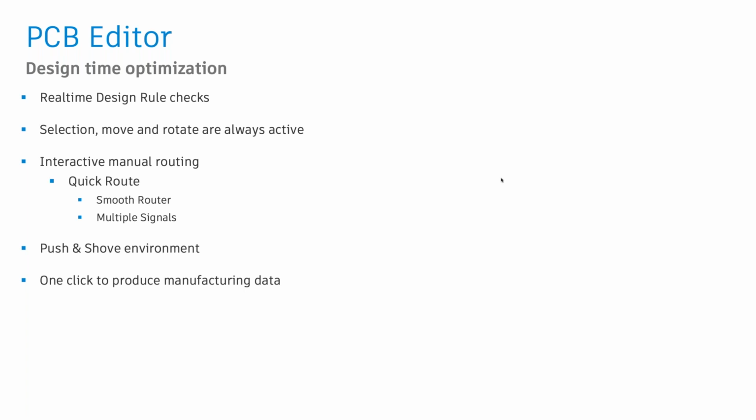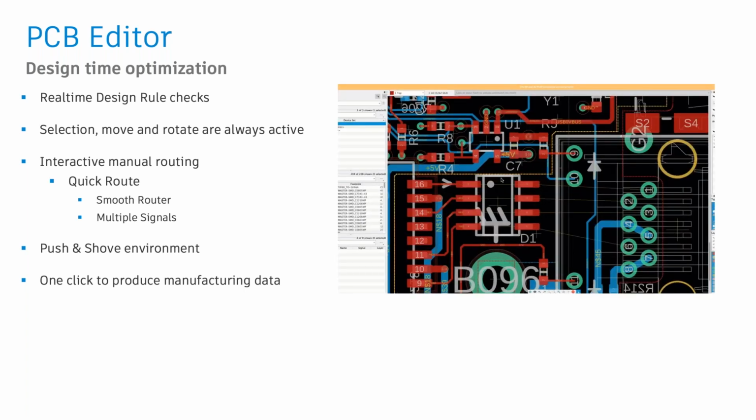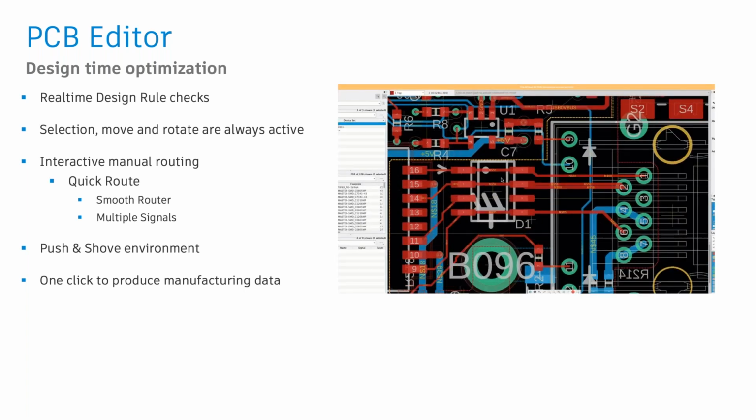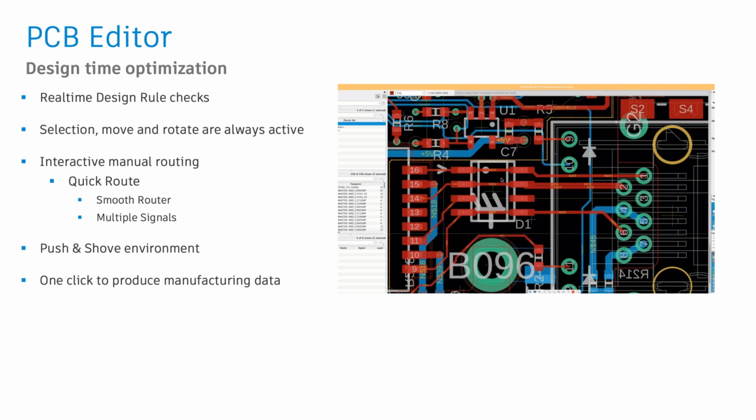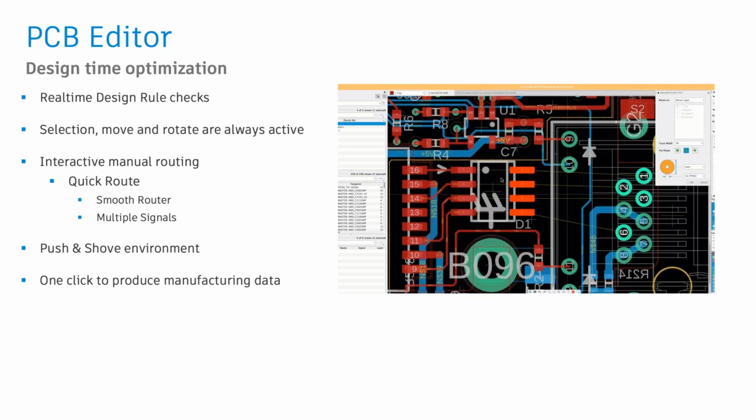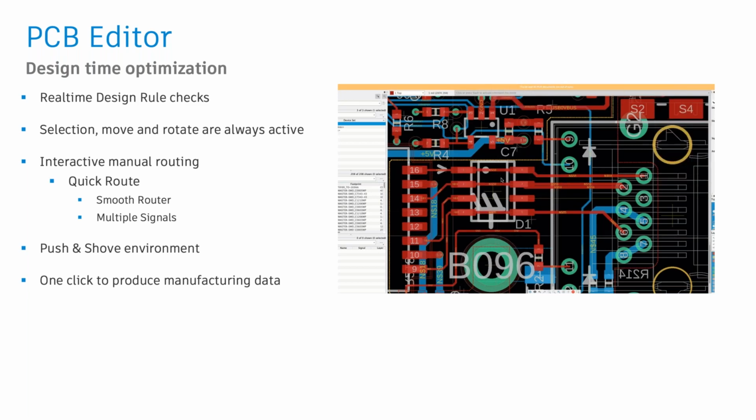The other feature that we have, which is actually very elaborate, is our routing capabilities. When it comes to routing, it's maybe the hardest part of PCB editing. Now, we've added a significant amount of routing capabilities to Fusion 360 to optimize this process, such as being able to route multiple lines simultaneously, and we're able to route multiple lines and give them guidance, so that they can follow a predetermined path defined by the user as well.